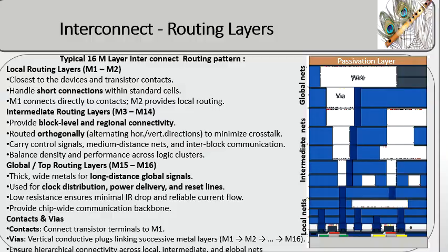Depending on the technology node, multiple interconnect layers named M1 through MXX are stacked, each with different dimensions to serve logic cells, power straps, clock network and power rings. The power distribution network delivers power across the die, and the clock distribution network carries the external clock signal into the chip. The clock tree propagates the clock signal to the pins of logic gates, ensuring coordinated switching.